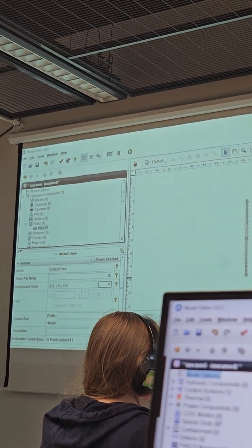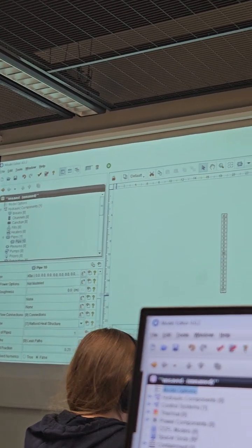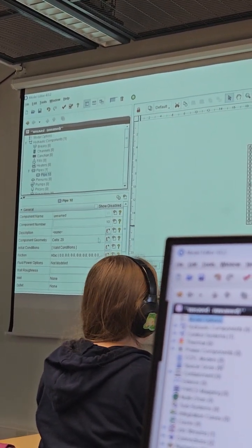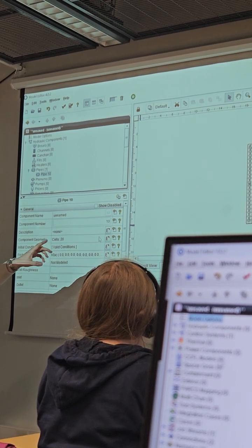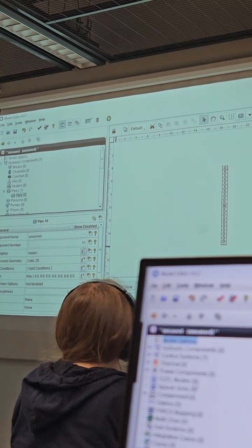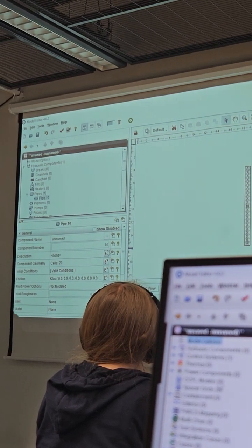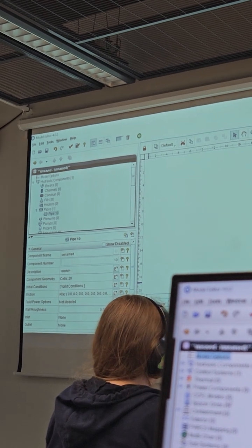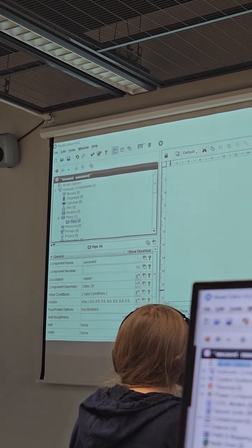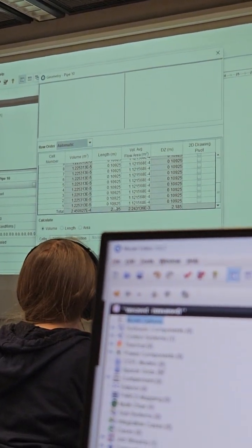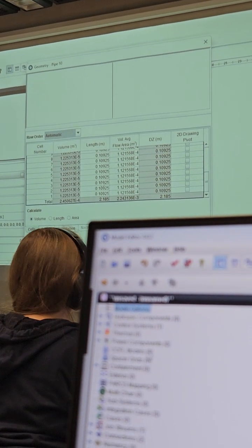millimeters. To make it easier to calculate everything later, we can remodel the pipe and change the cell size to make it like 470, then 1550, and the rest. I don't remember how much. So we just need to click on the component geometry cells and change the size of the cells. They're going from bottom to the top.